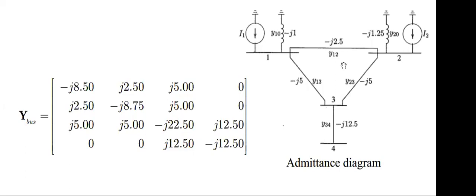Then after the reactance diagram, we can generate the equivalent admittance diagram. Then from that admittance diagram, the nodal equation, rearrangement of the equation, then the Y bus extraction or the coefficient matrix will give you your desired Y bus. That's the objective, that's your target. This is actually the starting point. Up to now, this Y bus is the very starting point of this course. All these steps are actually the starting point.